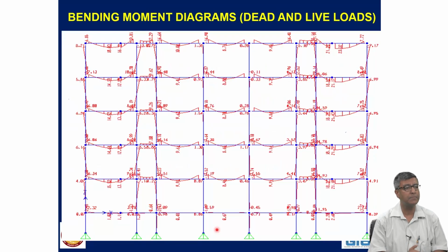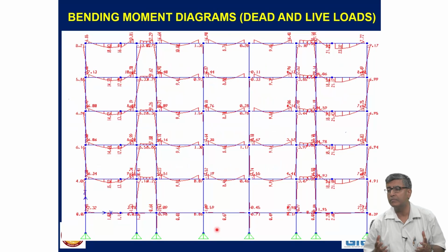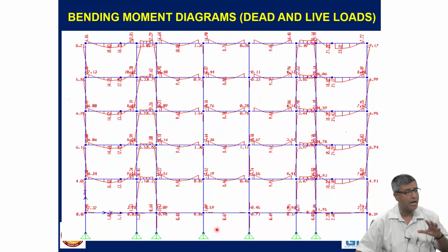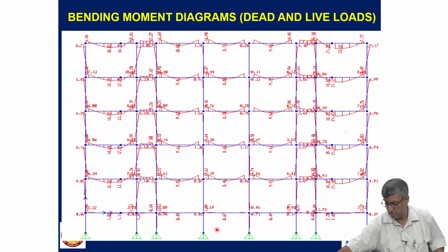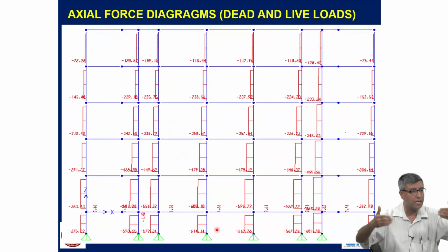And these are the bending moment diagrams. Try to have a feel whether this diagram makes sense or not under the gravity load. Similarly, the shear force diagram and the axial force diagram. As you go down the building, the axial force is getting cumulative.